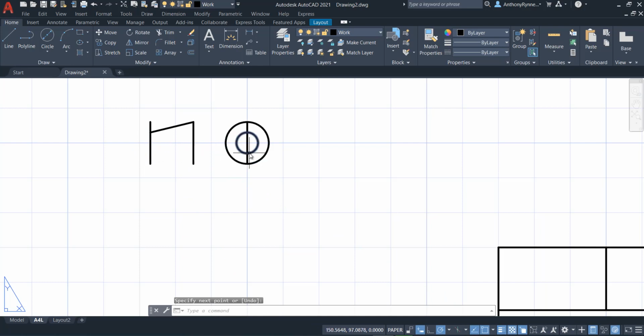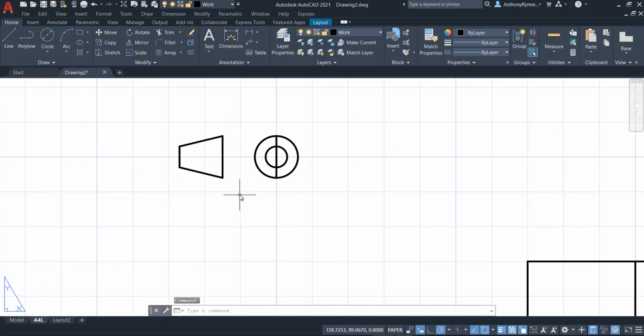And similarly, if I wanted to track of this quadrant point, I could have used intersection as well, of course. So just hover the cursor there, drag over, that lines it up for you automatically, and we'll draw our line like that. Trim away the bits we don't want. So you get a preview before you do it. And there's our symbol at the minute.